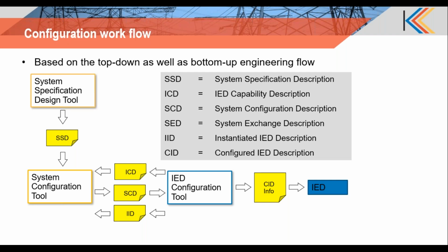Now, if there is a requirement of data exchange between these two substations, each of the SCT, the system configuration tool, should have some bare minimum information about the sources of data that are available in the other project. That means there should be some sharing of information between the system configuration tools. And it's never advised to share the entire SCD because that will contain a lot of information which is not really relevant for the receiving project.